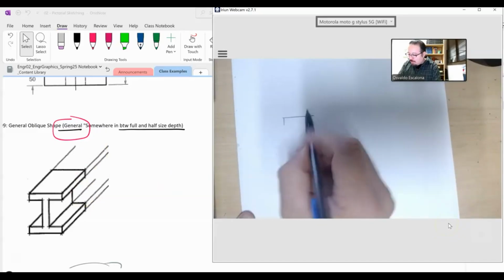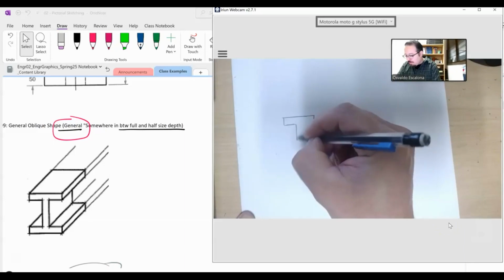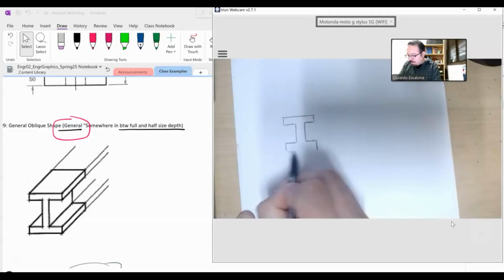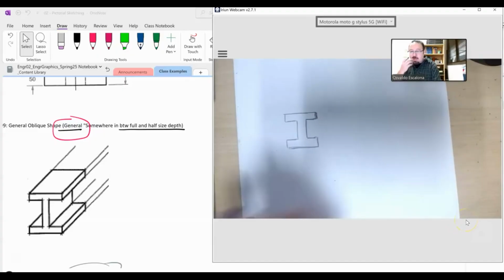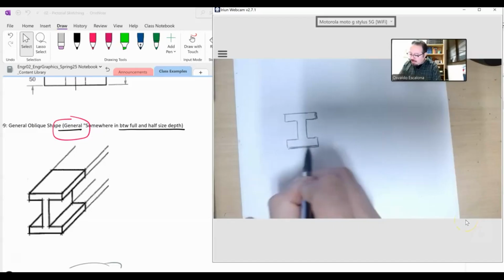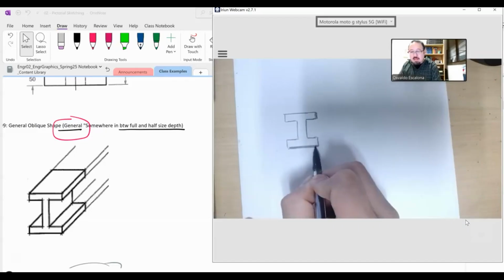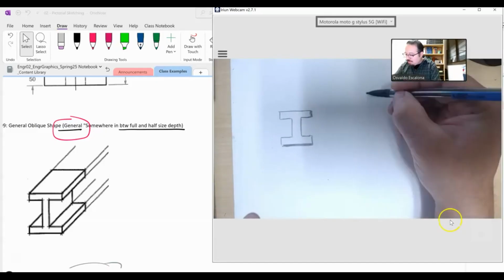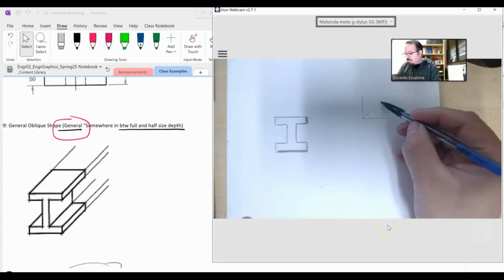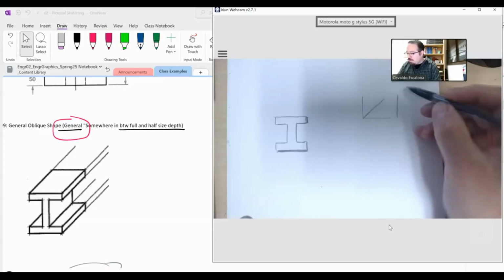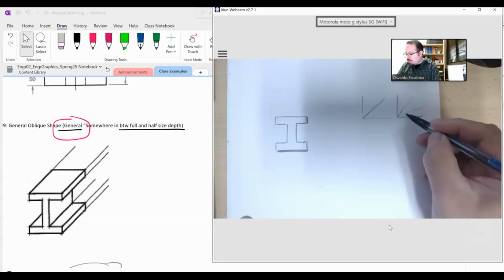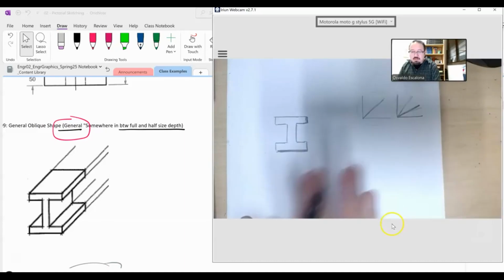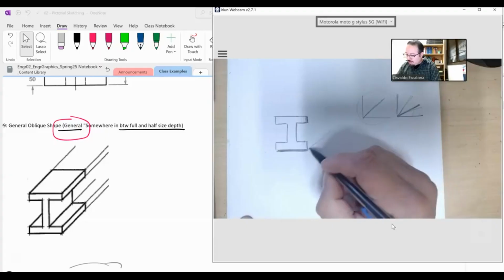when you make your front view, so I'm making it right now, and let's say my front view looks like this. And I want to do a general one, right? So general means I'm going to grab this, which is my width, and I can get the depth. And this angle is usually about 45 degrees. So what is 45 degrees? If that thing is 90, 45 will be somewhere in the middle, right? It's the same way that if I want to do 30 degrees, I can split that into 3 parts, and that will be about 30, about 60, about 90. In my case for the oblique, they're usually about 45 degrees. So 45 degrees will be about there.